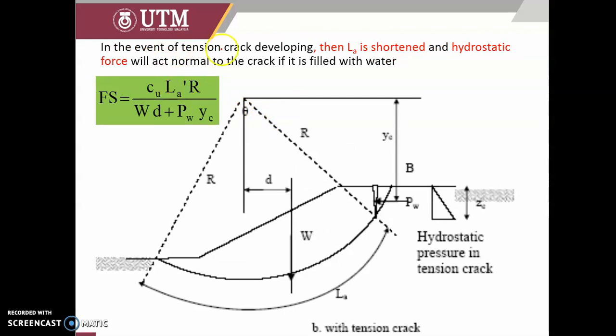Alright, so when we have a tension crack developed, either we have a water pressure or not, it becomes a pressure that tends to add moment, times the YC, the height. So this is the moment which tends to induce the failure. So the bigger the crack, the more danger it gives to the condition. But we also need to check the weight of the region, because the weight is also reduced.